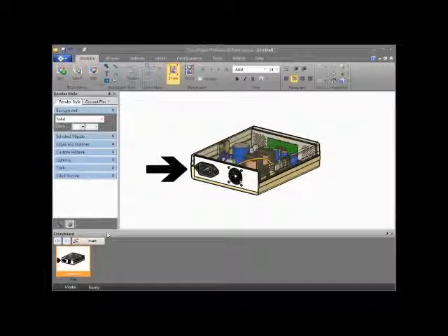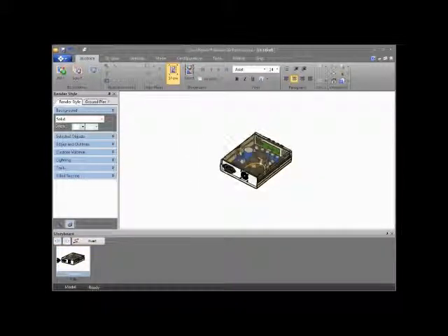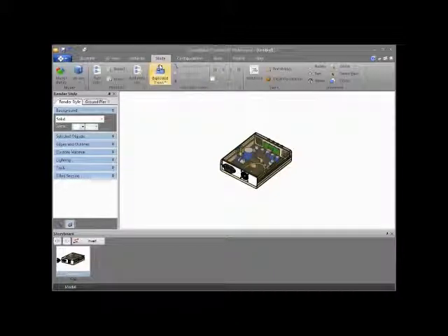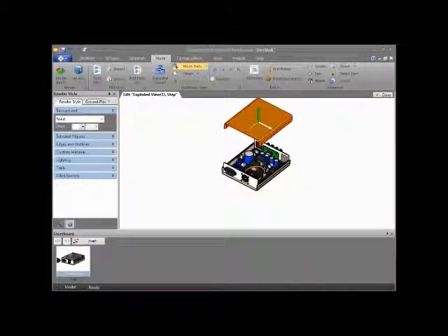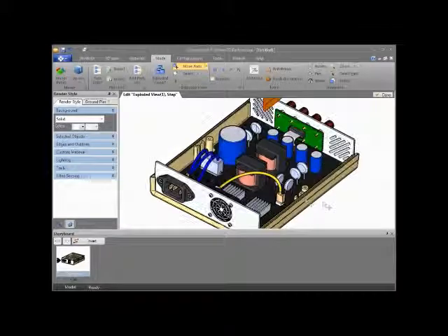Excuse me. For the second illustration, we're going to create an exploded view, and then we're going to add balloons to that. So it's a short little process here. We're going to hit Escape to deselect this one, and then we're going to create our exploded view. So under the Model ribbon, we have a set of exploded view tools. We can create a new exploded view. We'll just take the default name, and we're going to start by pulling components here.